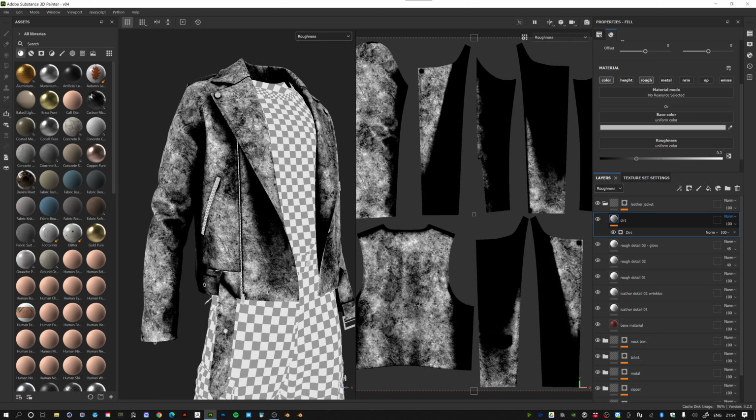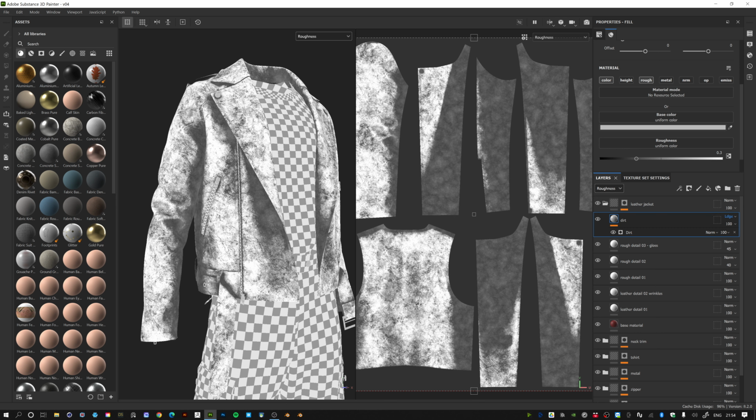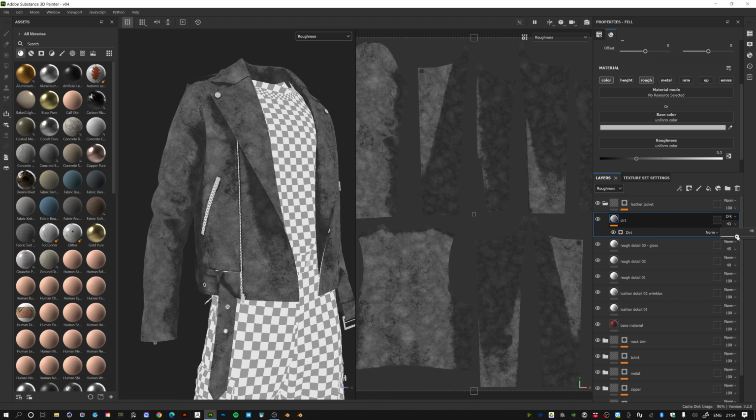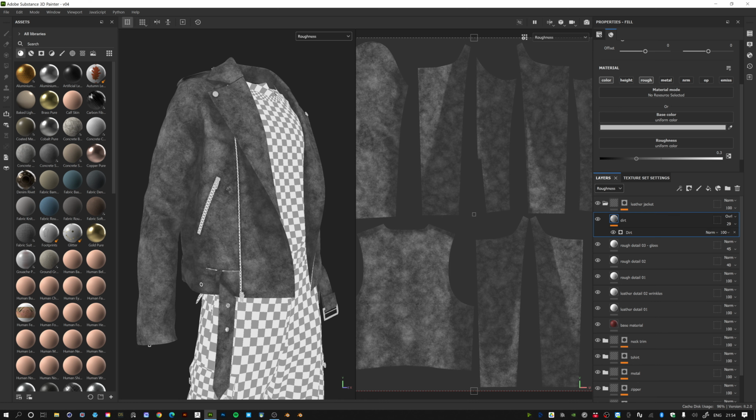Again, this is off the screen recording for some reason. I'm going to use add to start with, so linear dodge. And then I'm going to reduce just the intensity of this a little, maybe down to 40, a bit lower, so that this is starting to blend back in with our previous roughness map. I'll look at some different blending options. Maybe darken. No, too dark. Overlay. See how overlay works. Use overlay with like a 31% value.